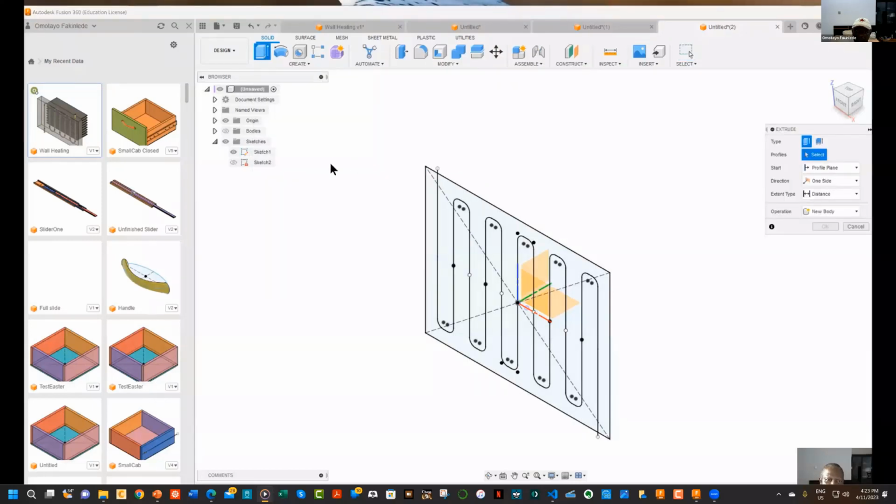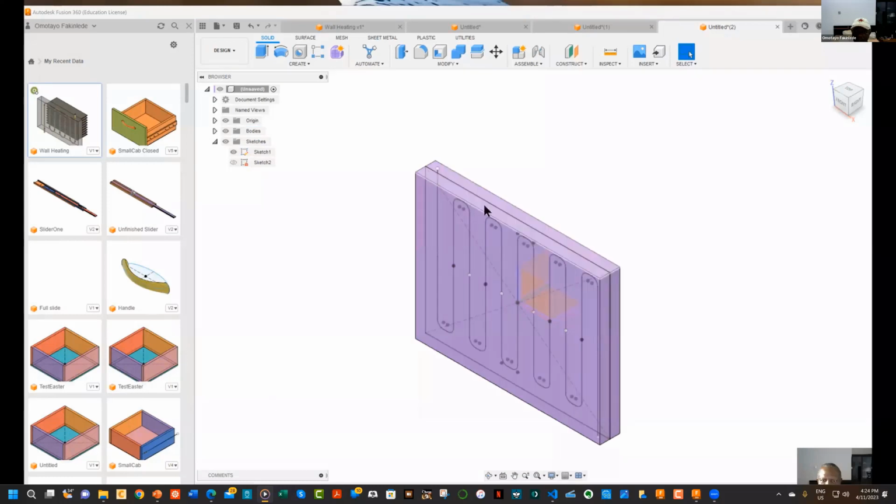Okay, create an extrude, and after we have created an extrude, we are going to extrude this outer profile. When we do this outer profile, we can cancel that because I've done it, and that will give us this body. The body is obtained by moving 25 on both sides. So that is the extruded body based on the outside profile.